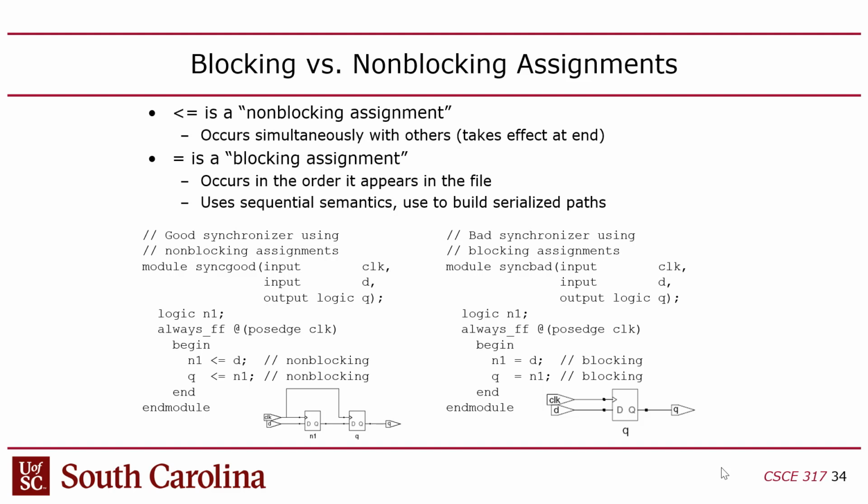However, instead of blocking versus non-blocking, in VHDL, inside of a process, you can create a variable as opposed to a signal. So these are signals. These are actual wires. So when you synthesize, this N1 will be a wire on the FPGA. It'll be assigned a wire, right? But in VHDL, you can actually have a variable defined inside of a process, which then behaves like you're doing blocking assignments on it. So in case you ever look at VHDL and you wonder what the difference is between a signal and a variable, that's the difference. It's basically the same as the blocking versus non-blocking, right?